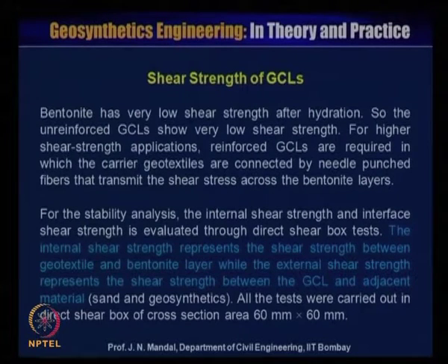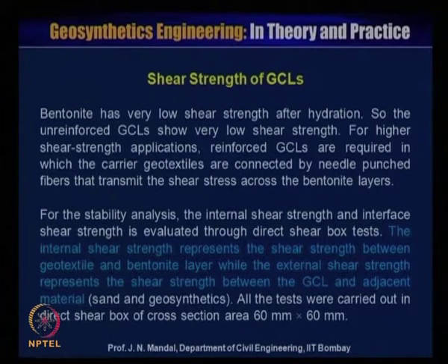Bentonite has very low shear strength after hydration. So, the unreinforced geosynthetic clay liner shows very low shear strength. For higher shear strength applications, reinforced geosynthetic clay liners are required, in which the carrier geotextiles are connected by the needle punched fiber that transmits the shear stresses across the bentonite layer.